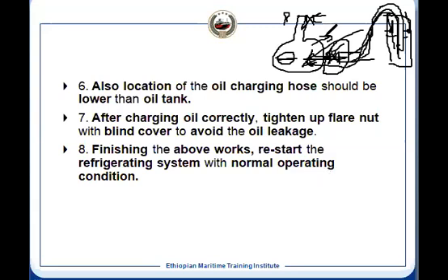We shut the suction and discharge valve, and then your crankcase pressure is higher than the atmospheric pressure because it is pressurized by the refrigerant. Now, if you open the drain valve, there will be a drain valve. Once you open it, with that pressure the oil will come out. You collect it in a container, and then the pressure will keep on reducing in the tank. Now, the suction and discharge valves are shut, so there will not be any flow of refrigerant inside. So the pressure will drop. After that, you will see the pressure will equalize.